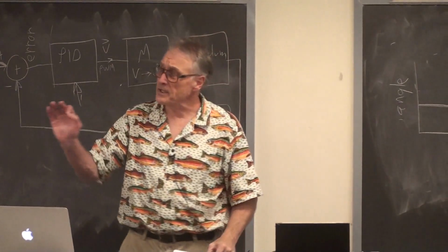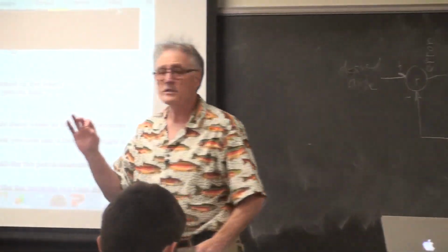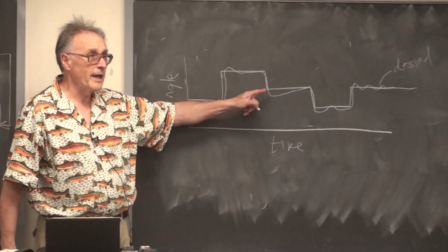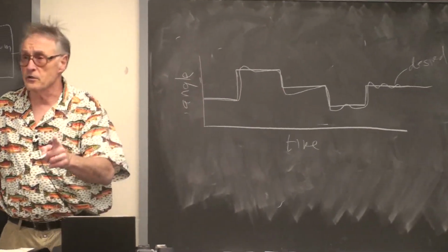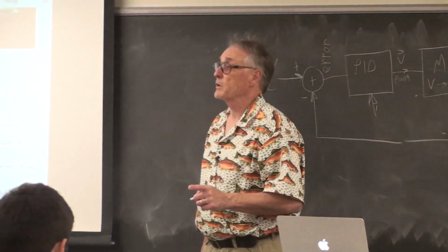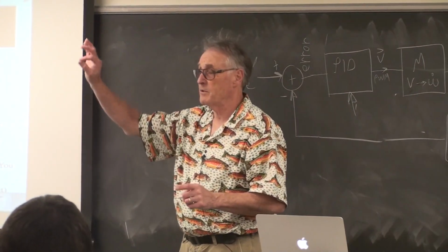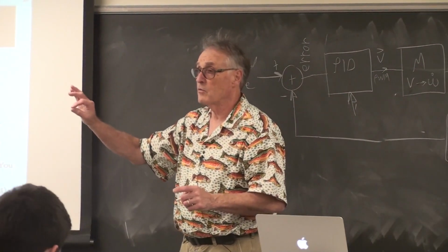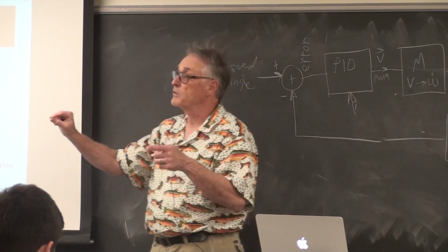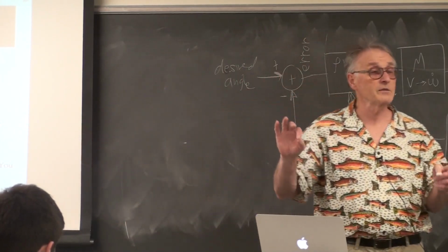And because every step of writing this code and making it run is going to depend upon you knowing what the motor response is and what the actual angle is, the first thing you're going to do in the interrupt service routine is get the plotting functions working for angle. So that when you move that beam by hand, you can watch the angle change on the oscilloscope. When you change the voltage on the motor, you can see the motor parameter change. Once you've got that running, then you can feasibly debug the system.